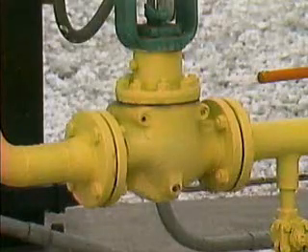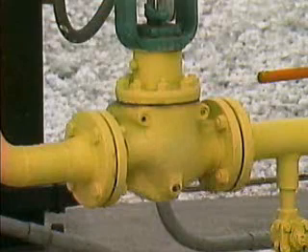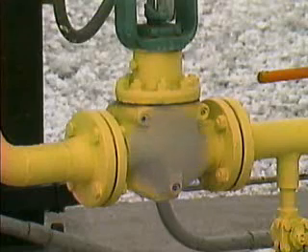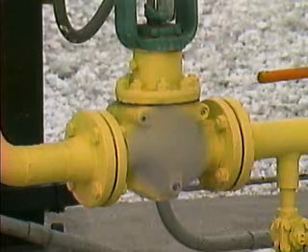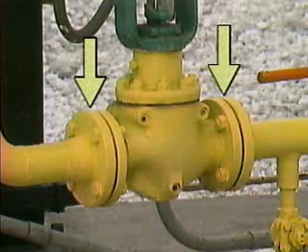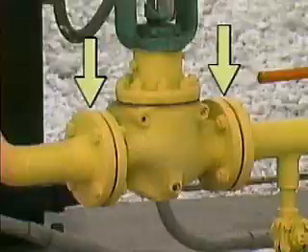The same valve can often be identified in several different ways. For example, this valve can be called a fuel flow control valve because its function is to control the flow of fuel to a furnace. It can also be called a globe valve because of the shape of its body. And it can be called a flanged valve because of the way it connects to the piping system.